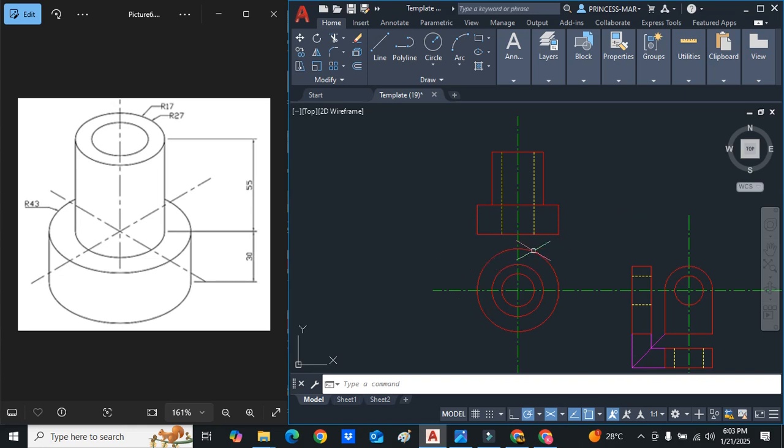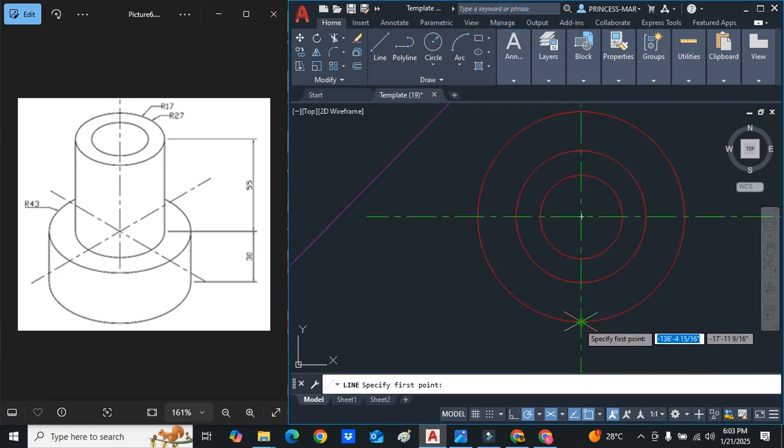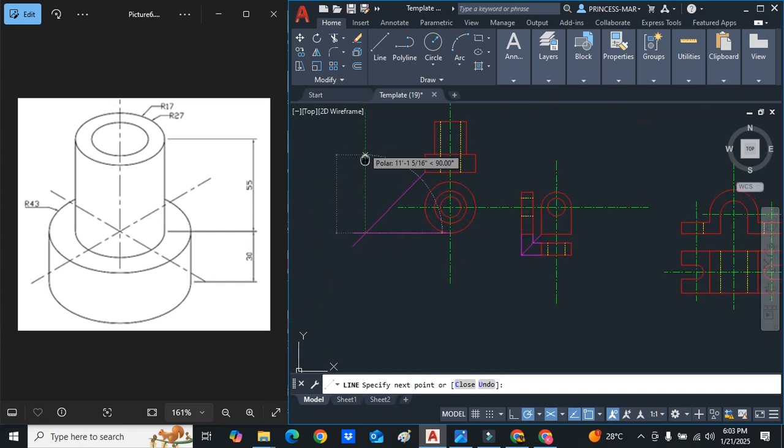Now, where are we going to put our end view? Our end view, as we said, it doesn't matter if the front is this side or this side, we're going to see the same figure. So I'm going to put the end view across to the left. I'm looking for the 45-degree line. And then I am projecting. The reason that we drew the circle first is because you're projecting from the circle. So you always project from your circle.